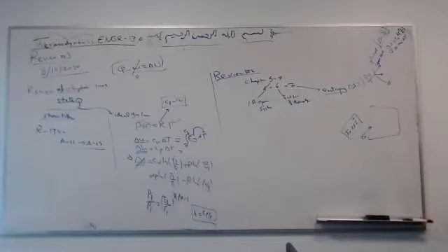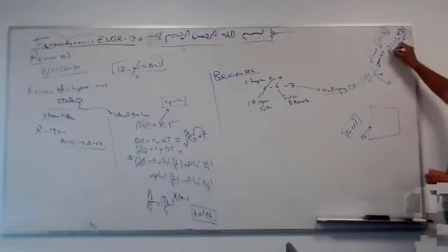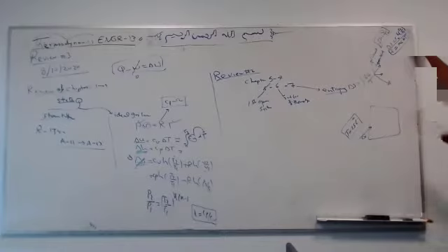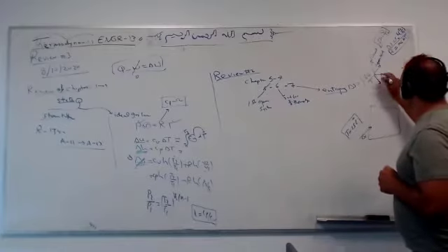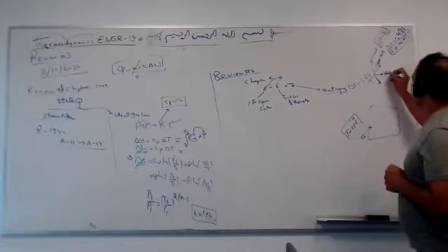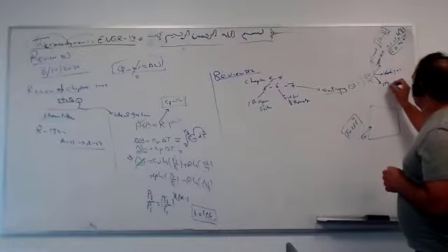The same for solid. If you have a bar of metal, let's say aluminium, aluminium has heat capacity, I think it was 912 joule per kilogram Kelvin, multiplied by the mass of the aluminium and delta T. Let's say you heat it from 30 to 100, 200, as long as it's not at the melting temperature and it is within the solid phase, it is always MC delta T, for these materials. Then we took two things: one for ideal gas and one for the steam table.